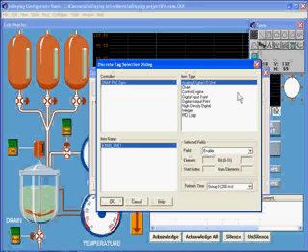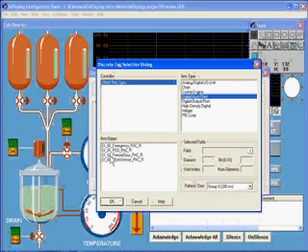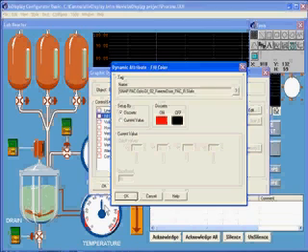Here's the true beauty of ioDisplay. Since ioDisplay is so closely integrated with ioControl, you have immediate access to all of your control program variables and I/O points. There's no need to retype tag names or configure a separate HMI database. Simply select the type of data, the tag name, and change the refresh rate if you'd like. And select OK. Now you're done.